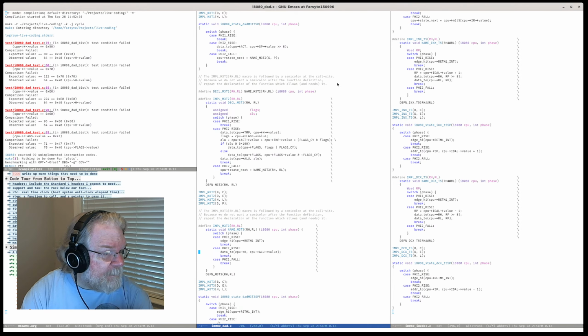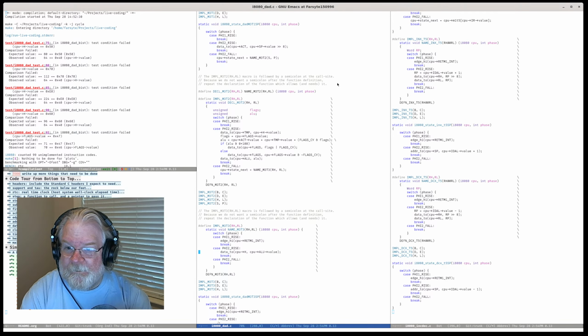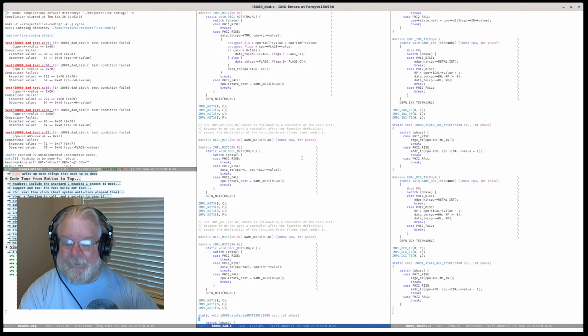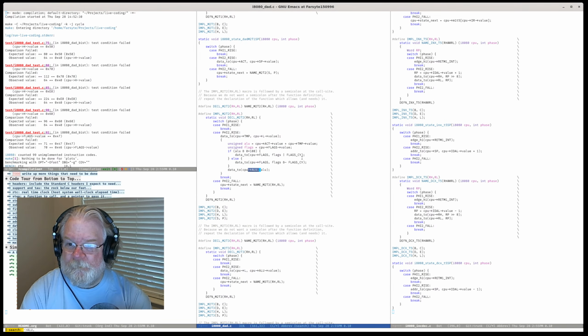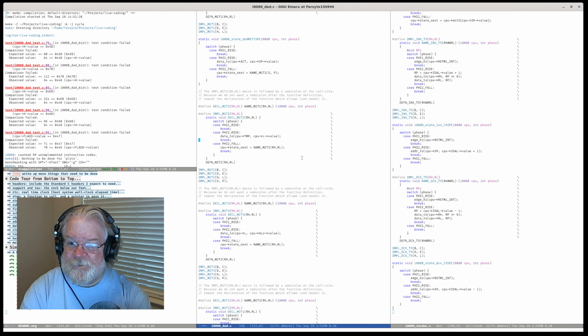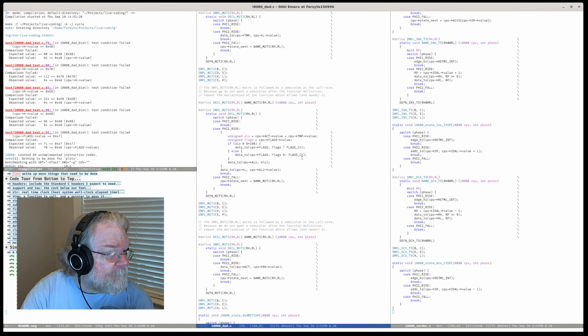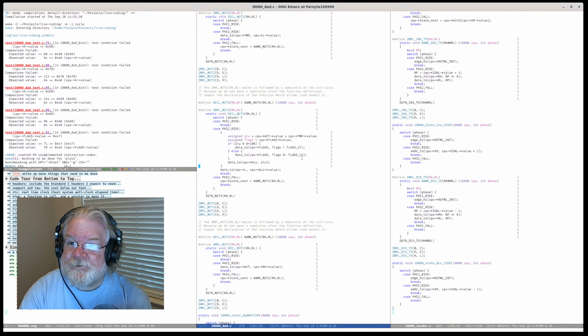Now I am actually committing the carry during the T2 cycle instead of the T3 cycle. And that's because I don't really want to defer this. I could get it done in the right cycle by deferring the ALU work. Do I want to do that? Yes, I want to do that. So this bit of work here gets moved from M2T2 to M2T3. Actually, it has to happen twice.